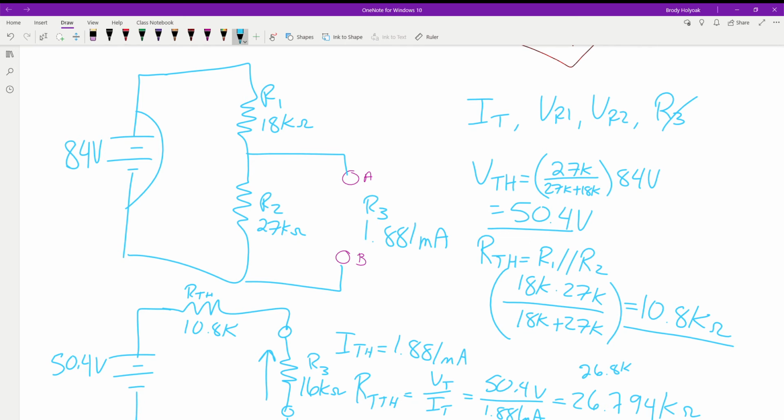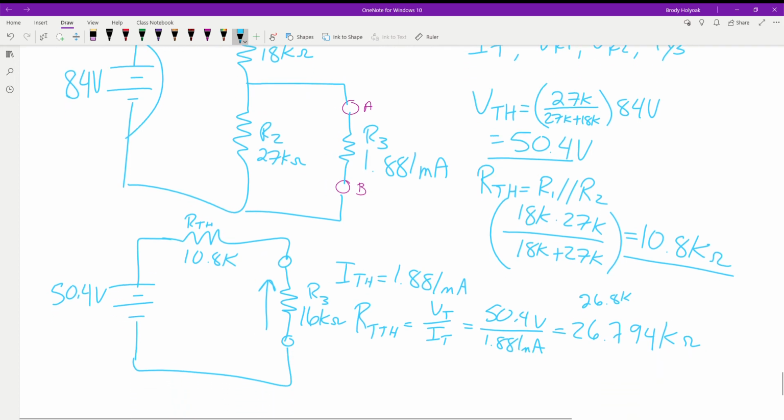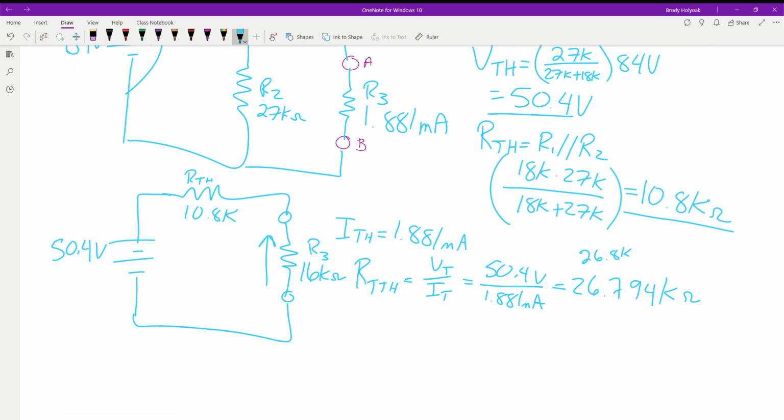So now we come back to our original circuit. We plop this guy back in, and we know 2 things. We have 16K ohms here, but what also can we determine? The voltage drop, which we could have also gone this direction as well. We could have gone through and found the voltage across this guy, subtracted it from our total in Thevenin, and that would have given us the leftover here, which then we wouldn't have to calculate again because we'd have that value. But like I said, we can go about it either way, solving for total resistance, solving for total voltage, and subtracting out that way.